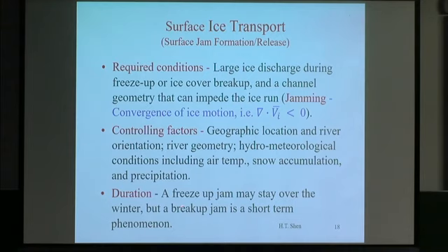Freeze-up jam and breakup jam, mechanically they are the same thing, okay, except the effect of the thermal. One is freezing, one is melting. And once you get a freeze-up jam, it stays there over the winter, and breakup jam, of course, will release, so it's a shorter term. And the river ice people most of the time are thinking about the problem with the breakup jam, but with the lack of ability, that put it more straightforward, on fracture and all these things, the breakup side we know very little.